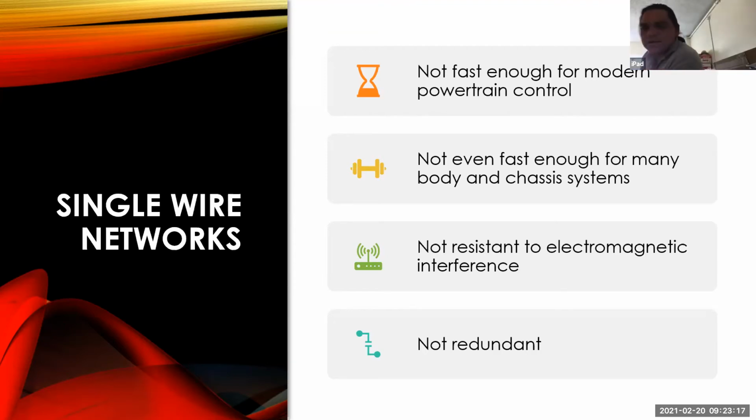And of course, everybody's shielded, right? Well, no. How can we get this high speed? What's the frequency? What's the bus rate? It depends on the network. These are pretty low. CAN A is down at, what, 10 kilobits? That's not even really that fast. But it's fast enough to convey the information, and slow enough that the EMF is not as much of an issue.